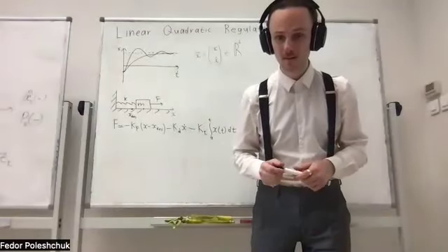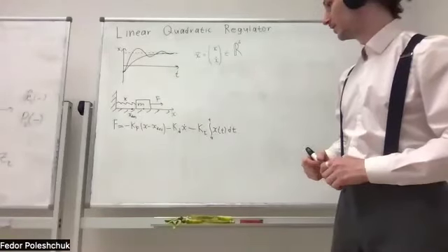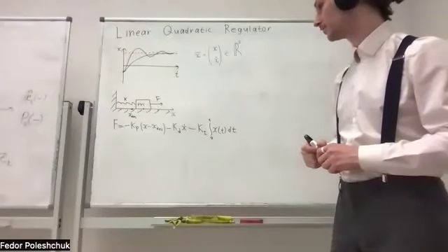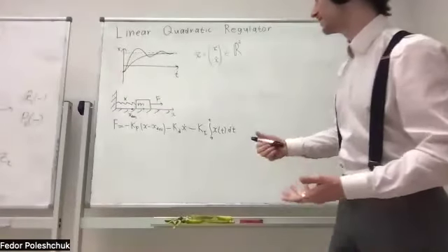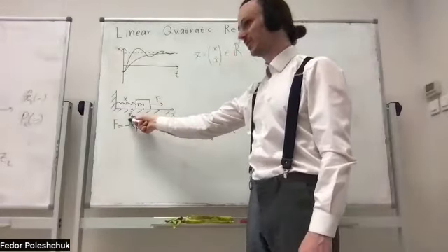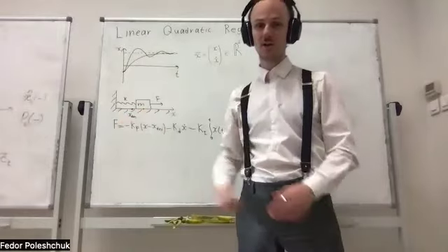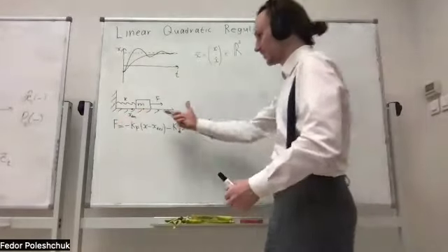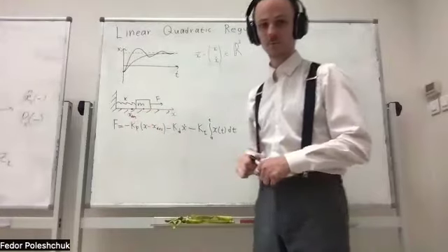Yeah. Okay. So x desired. So we are trying to calculate the force required, right? Exactly, so that we can move the block from the current position x to x desired, and also get it from the current state to the desired state that we want. Exactly. The current state is some x and some x dot, and the desired state is x desired and 0 as the velocity. We want to stabilize this block in a certain position.